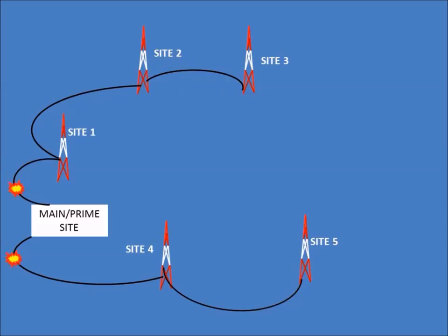Timing and reliable connectivity between sites is essential. Audio phase delays must be designed so that the signal arrives at overlap locations at the same time, and that the audio levels are consistent. Differences in audio phase and amplitude cause distortion in the received signals.